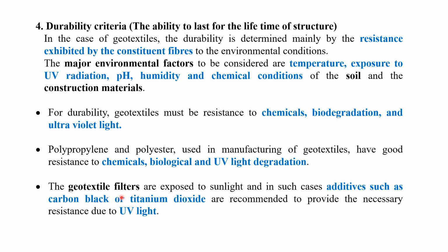The geotextile filters may be exposed to sunlight. Some additional suggestions are also given here. If geotextile filters are exposed to sunlight, in such cases additives such as carbon black or titanium dioxide are recommended to provide the necessary resistance to UV light.